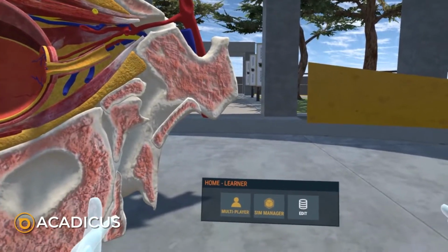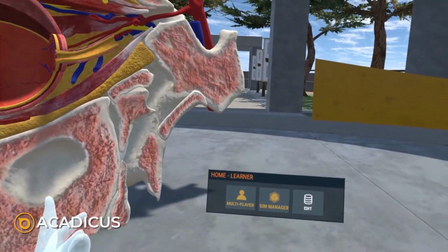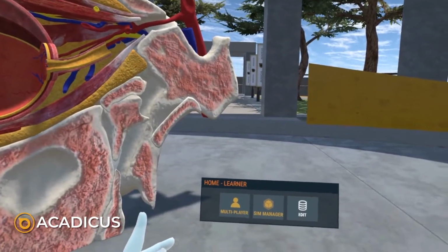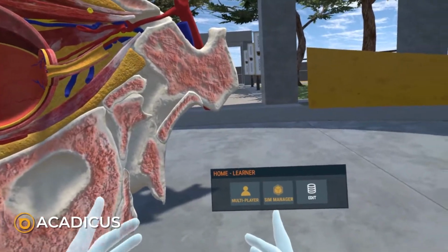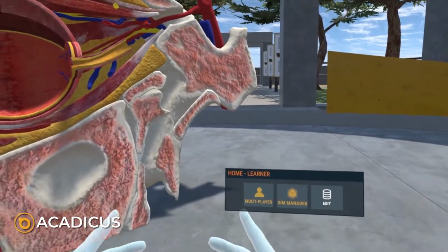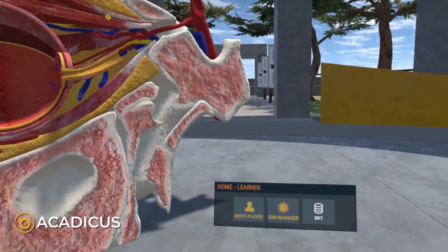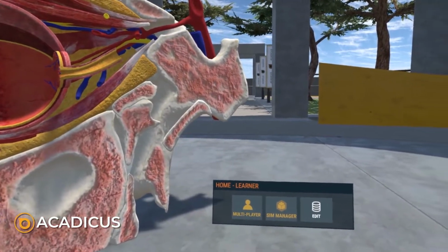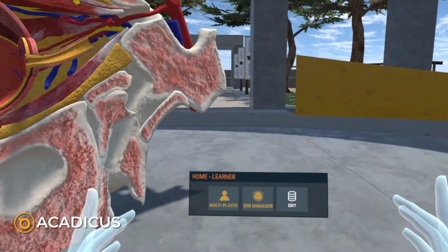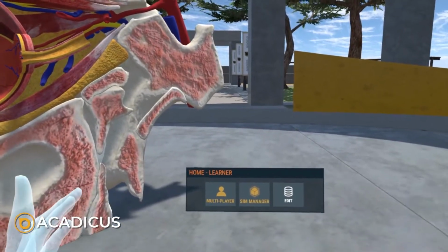You can also capture 3D recordings from non-VR mode. Sometimes that's easier. If you've got someone helping you, they can be in non-VR mode, and they can be in ghost mode as well, so that they don't show up in the recording, and they can manage the recording process if that's easier. But this tutorial is going to be covering 3D recordings in VR mode.